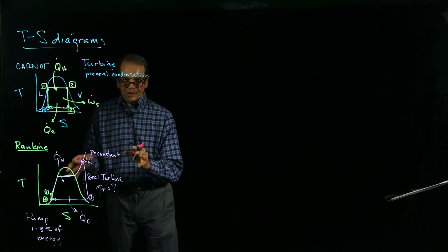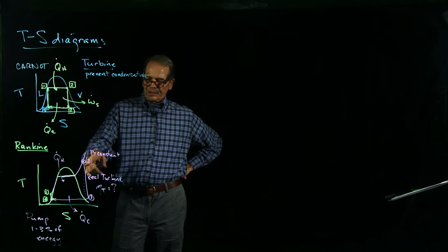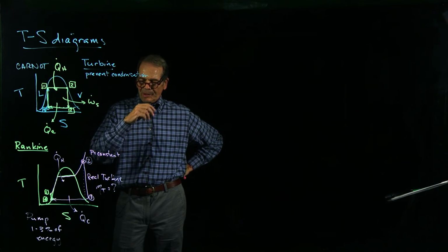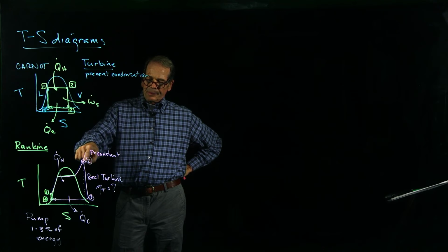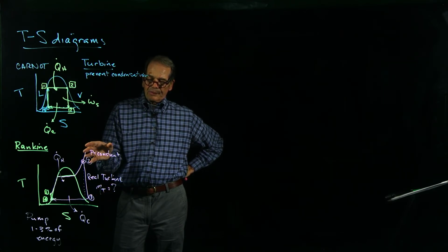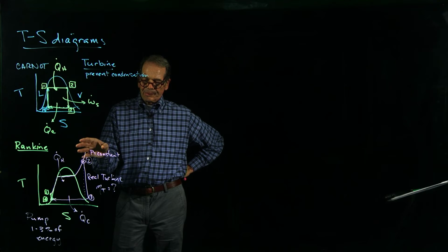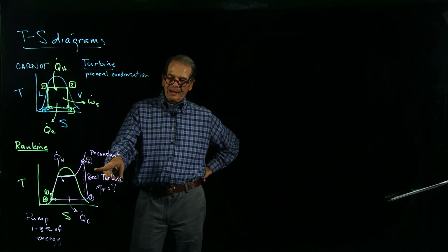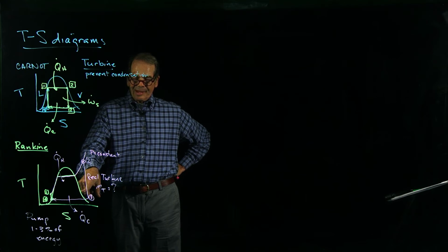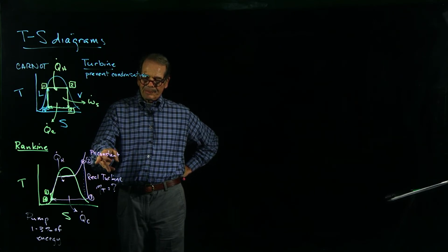Okay, well, this is nice, but we can quickly think of improvements. One thing is we are heating the fluid up to this temperature and pressure in one step, but we are constrained here by the need to try to prevent condensation in the turbine. So people have generated another solution, which is called the Rankine cycle with reheat, and this uses 2 turbines. One, a high pressure turbine, so it can heat it up here, drop down to maybe there, and then what if I took this same fluid, this is at a lower pressure, and heated it back up again in the furnace?